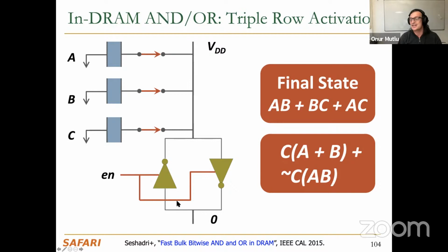This is the sense amplifier enabling, which we didn't show perhaps. Normally there's an enable signal to the sense amplifier that's controlled by the DRAM chip. We're just showing it over here. So you need to enable the sense amplifier, but the DRAM chip enables the sense amplifier internally when you do the activation. Make sense?